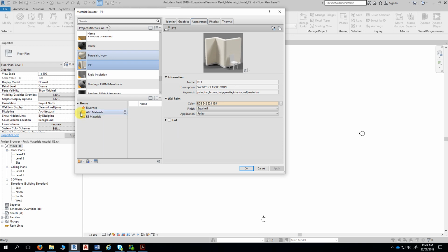To use the library, you go down to the button here, open existing library, find that file, and it will appear in your list down here, and you'll see all the materials over here from that ColourBond library. So in your assessment task, if you're using steel products, which ultimately you will, so roof covering, gutters, downpipes and fencing, you can take the materials from this library. All right.